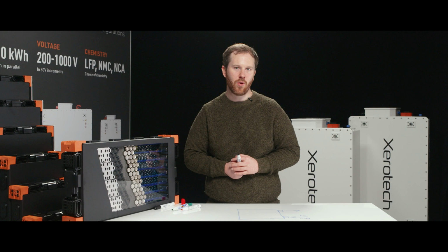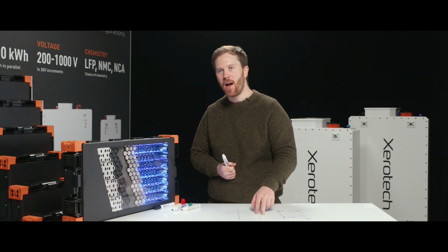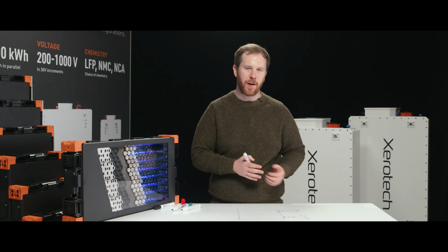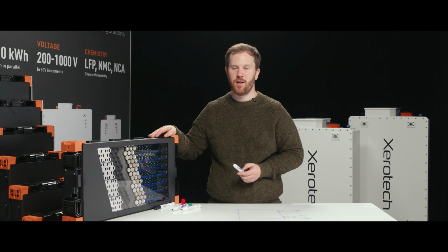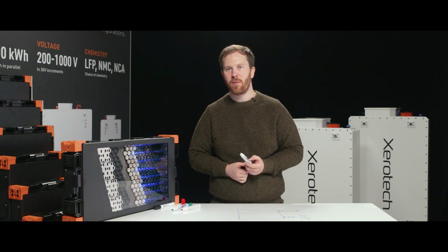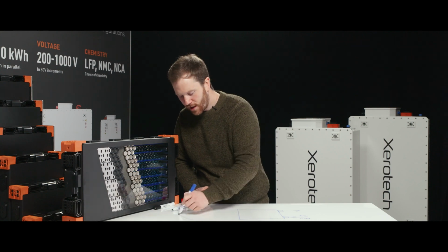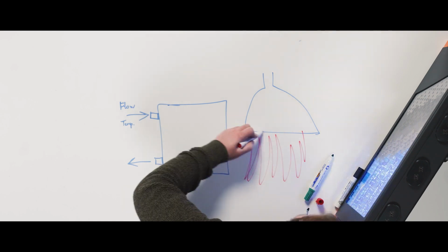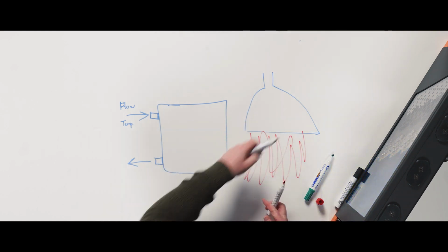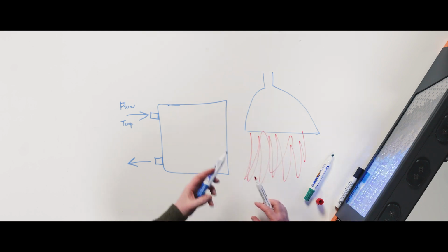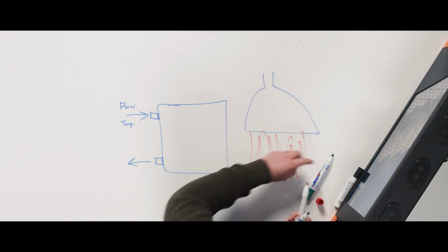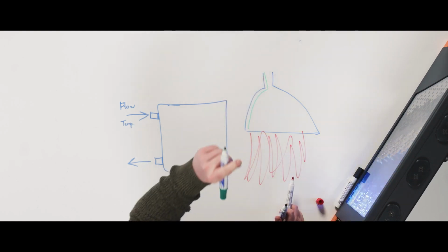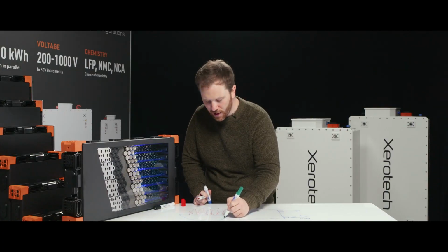There are different designs and more extreme cases here that you can have very high pressure drop systems that have much higher heat transfer coefficients. But the disadvantage of that is they result in very high temperature gradients. So to take the most extreme example, if you have a rocket engine nozzle that's shooting out huge amounts of energy out the back and heat, the rocket nozzle will melt. So actually what they do in rocket engines is they regeneratively cool the engine wall. So they basically flow the rocket fuel down the wall in tiny little microtubes that flows back again.